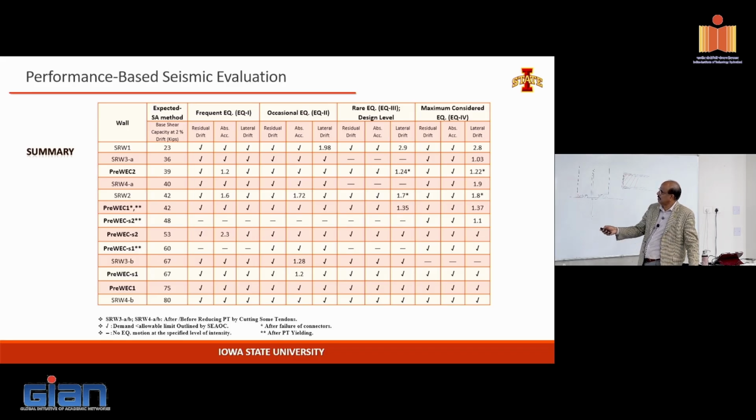Now you come to the single rocking wall, maybe you have more numbers exceeded, right? So there's all of them, lateral drift exceeded, but the wall didn't fall down, but it did exceed. So that's 1, 2, 3, 4, 5. There is a lateral drift exceeded here. Typically they actually went through a lot more displacement than we expected, or what the code would allow, or expect you to have. But the surprising thing was that the structure survived and performed satisfactorily.